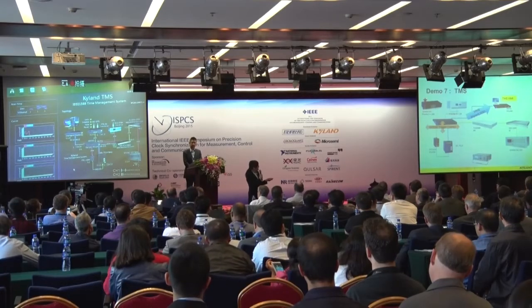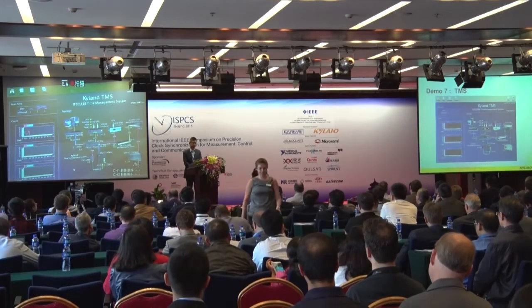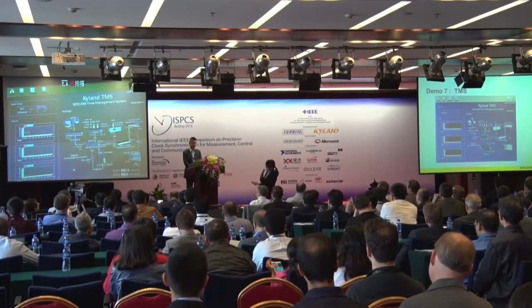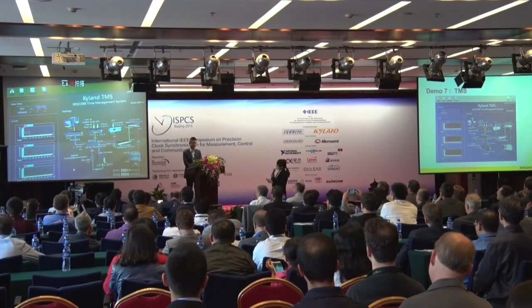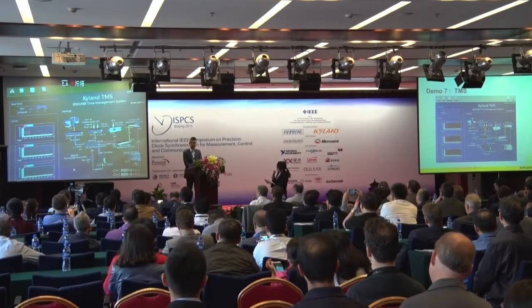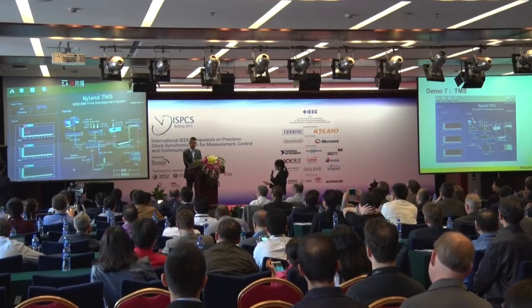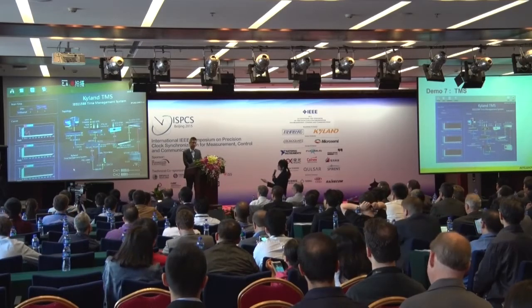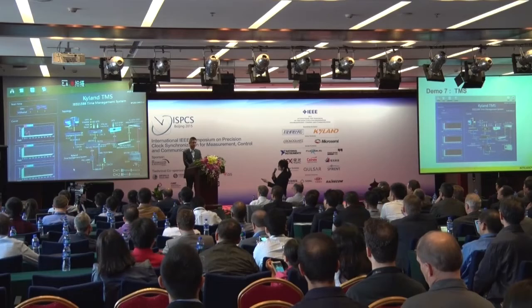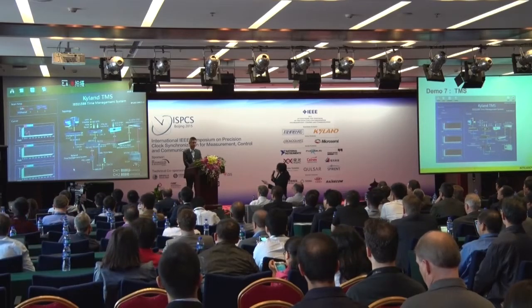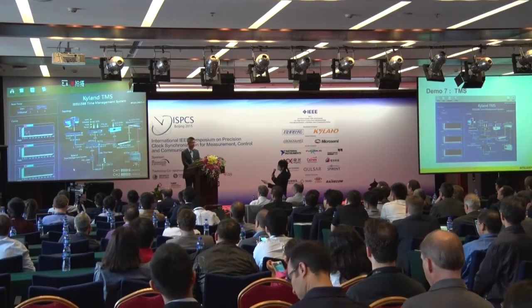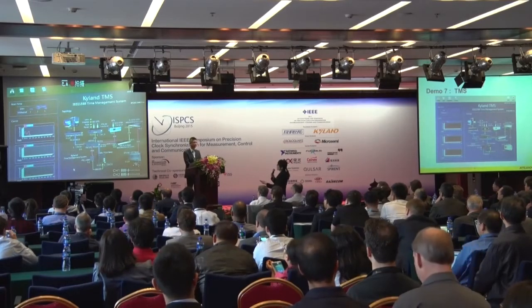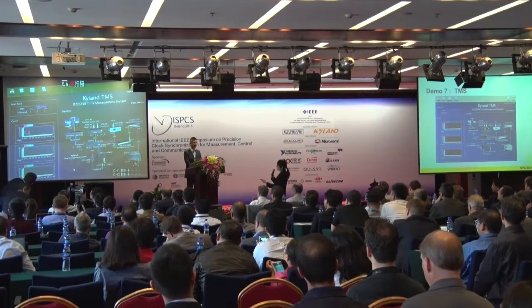And this is how the TMS HMI really looks in a real working system. In this TMS system, you can see there are different areas. This area is for the topology, and this area we check the real time deviation of different nodes. We have the master clock nodes, and the switch nodes, and we also have the end nodes, like the protection relays.